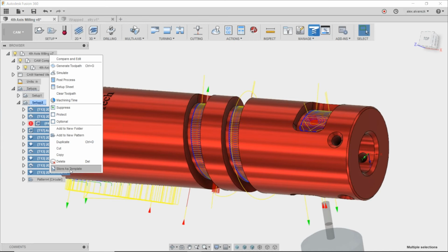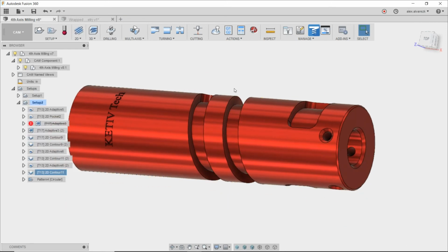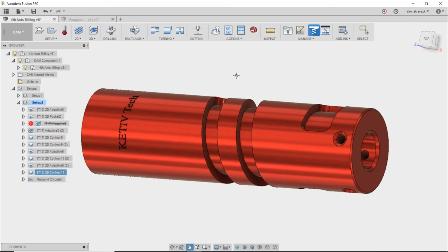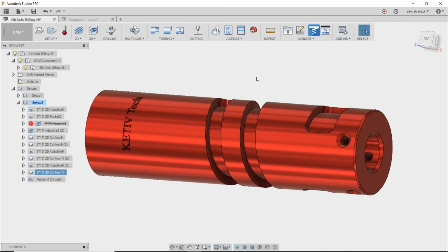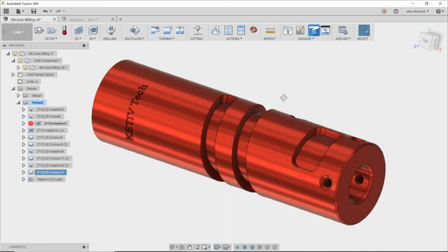So now when you're working on a part, simply select the chains that you want to machine, and then delete some of the toolpaths that you're not going to be using, and make much better use of your time that way, right? So that's another option to use. Control duplicate is a pretty big one for me.